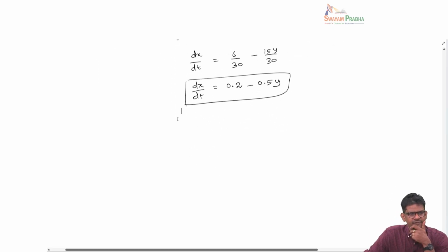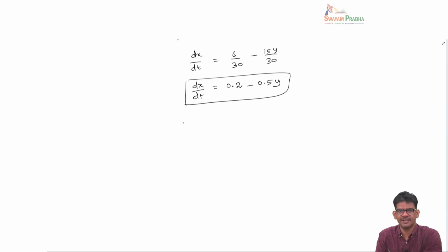So this equation tells me how the composition in the liquid is changing with time because of this operation, and that depends on the composition of the vapor y. This is where the VLE data will have to be used to couple the two. But in this problem, the relative volatility is constant.